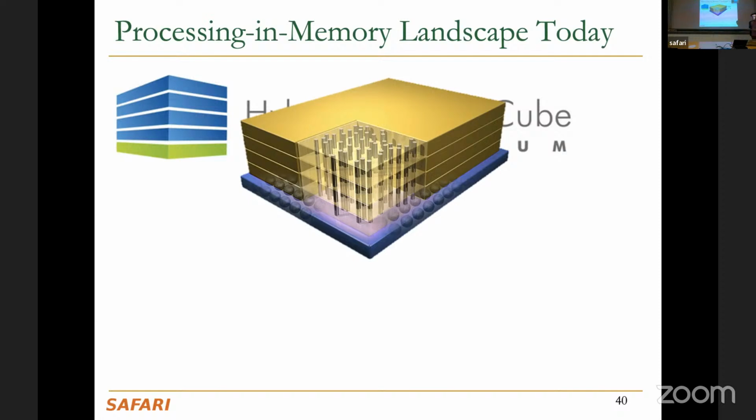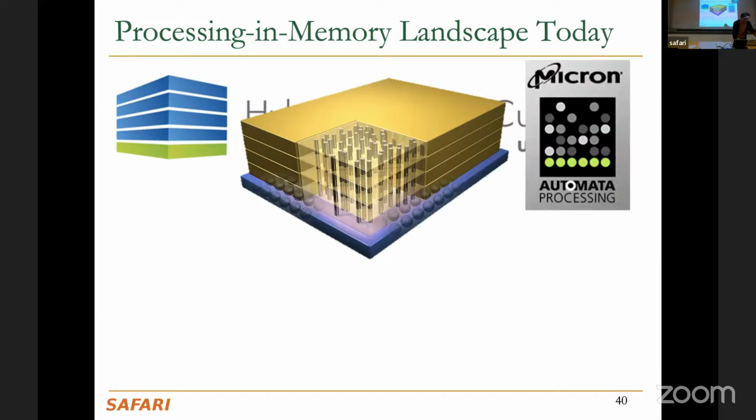So using these 3D-stacked memories can be a way of alleviating some of the scaling issues of memory. An additional advantage is that in the logic layer, where, as I said, we have memory controllers, there is some extra area that we can use to embed additional logic, some processing elements that can operate on the data they have direct access to. So it's one of the enablers of processing in memory.